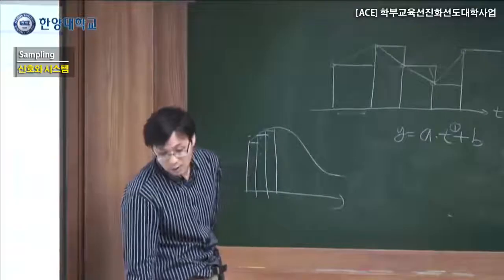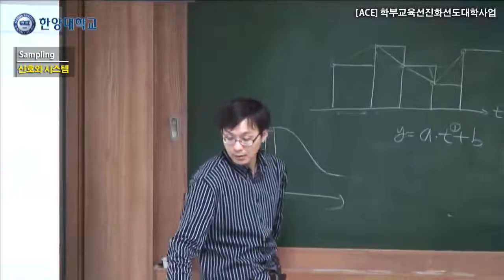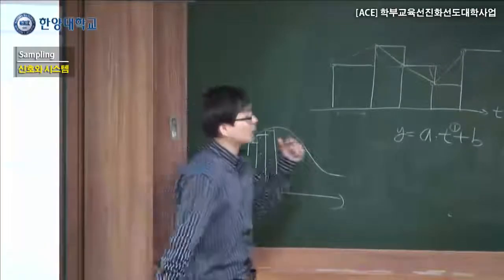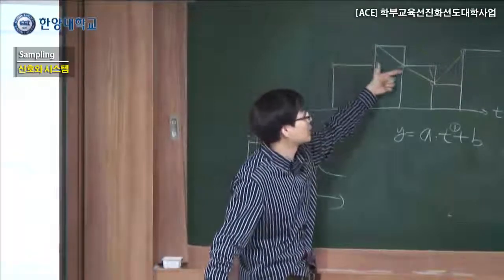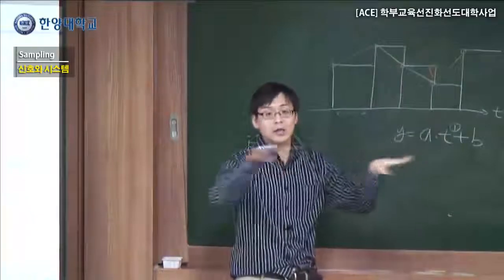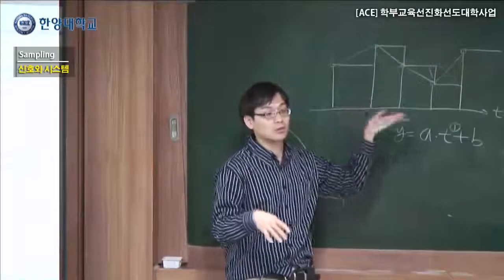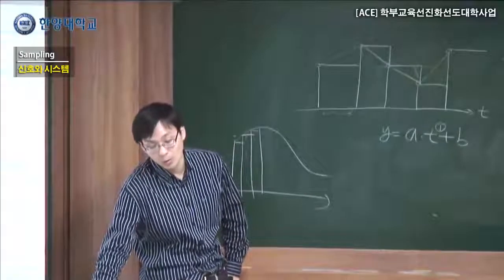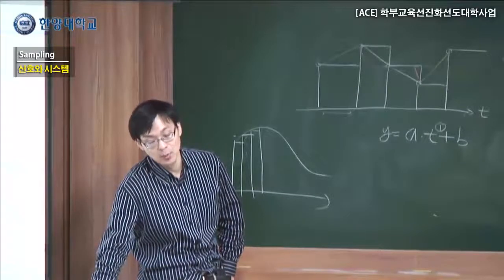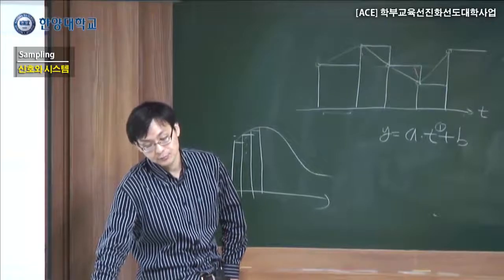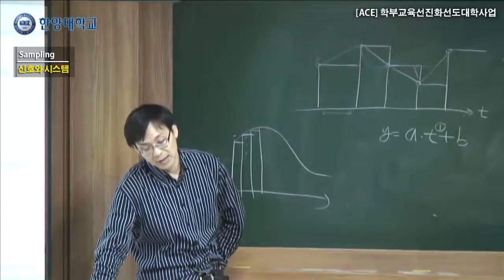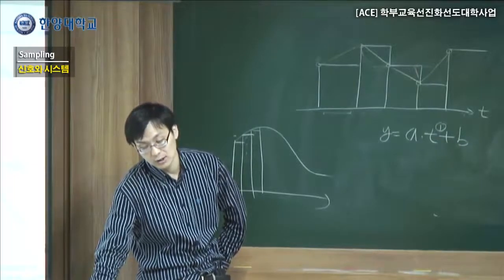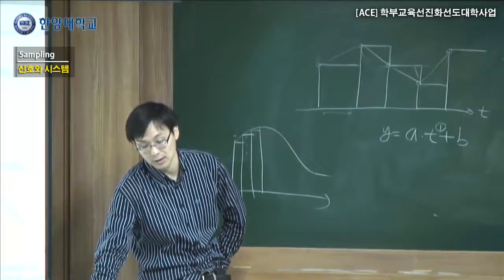So we are talking now about the first order hold, where we begin to draw a straight line between 2 points. That's why you can see this example, sometimes called linear interpolation. It's saying that we are connecting adjacent next data using straight lines. That's what you can see in here.